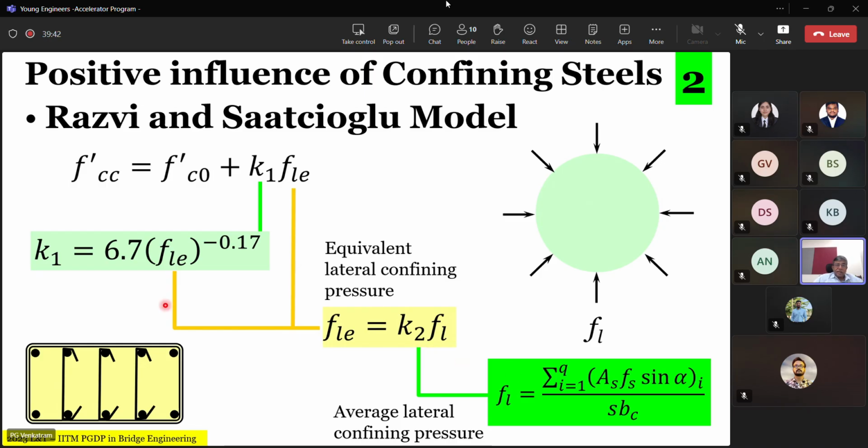And the fact that, for example, if you take a look at the stiffness of the transverse bar, if we call this transverse and this longitudinal, the transverse bars are more in area and smaller in length and therefore stiffer. So you end up having a higher value of stiffness in that direction.